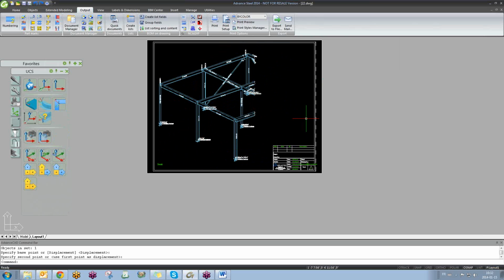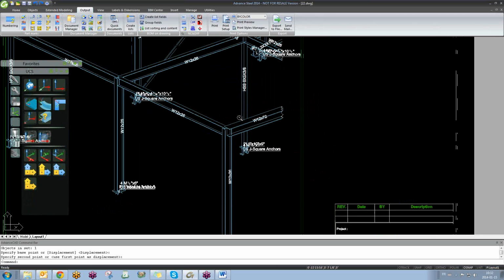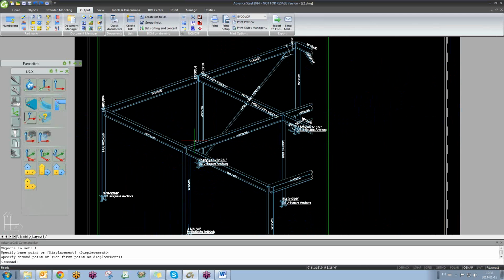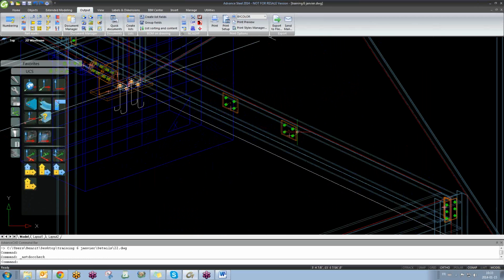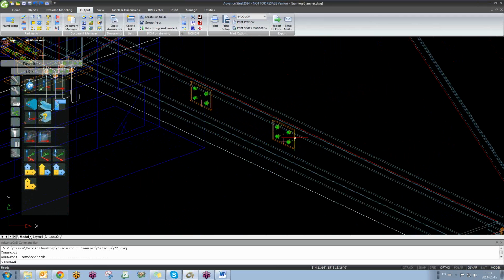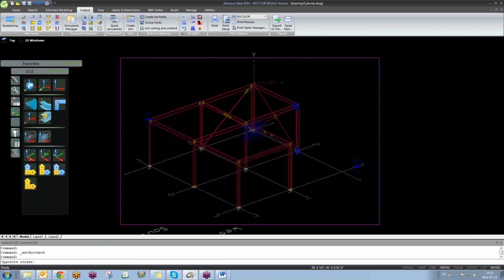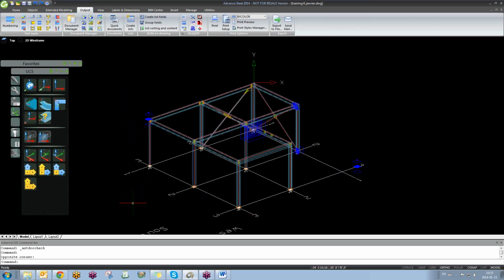In this case, what I would do, if there was a way, is turn off that layer. If I created that stair on a certain layer, and I don't know if we even talked about this, can I turn that layer off? Even if you turn the layer off here within the model, or you just hide the stairs and start an isometric view for the whole model, the stair will appear even if it's hidden within the 3D model.